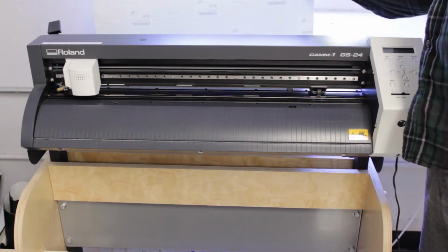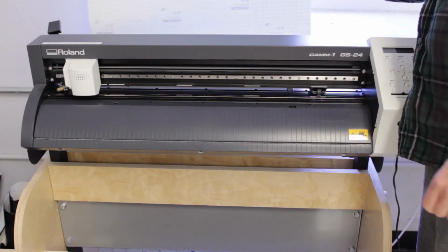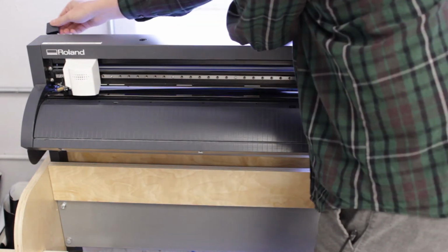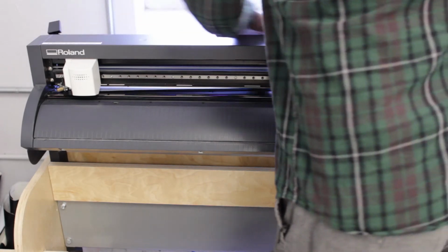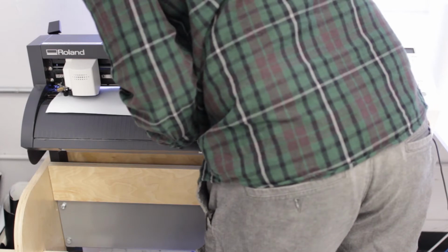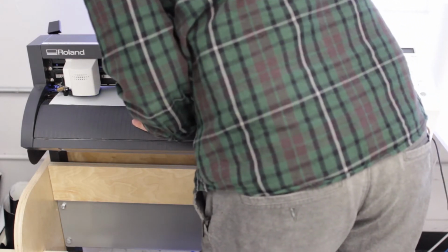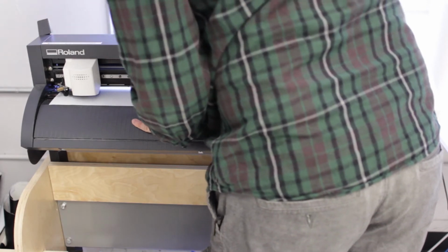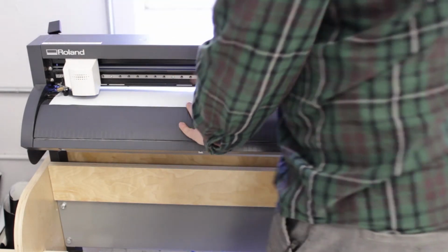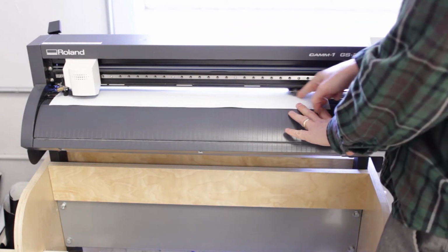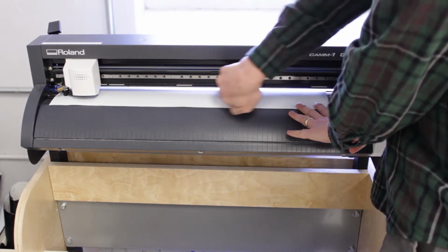When ready, make sure to prep the vinyl cutter before proceeding to cut your artwork. In order to load vinyl, you must lower the clamp lever at the top left-hand corner of the vinyl cutter. You may then feed the vinyl in through the slot of the machine. Make sure the vinyl is sitting perpendicular to the machine's axis, and move the wheel bearings to the edges of the paper.